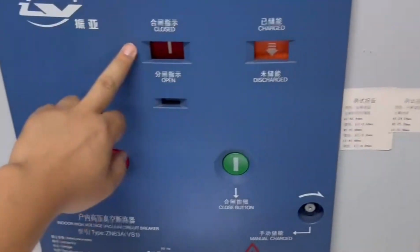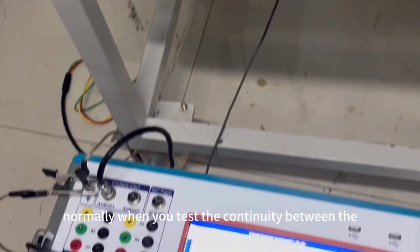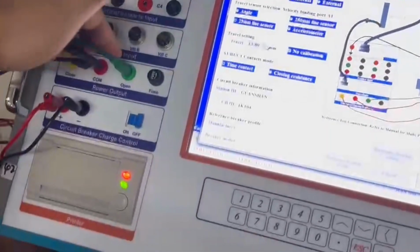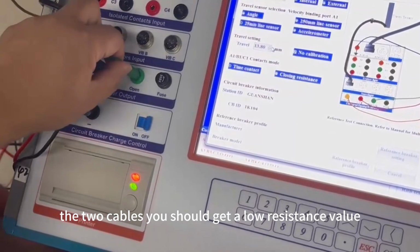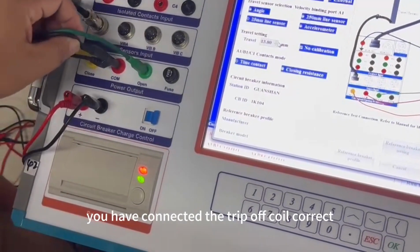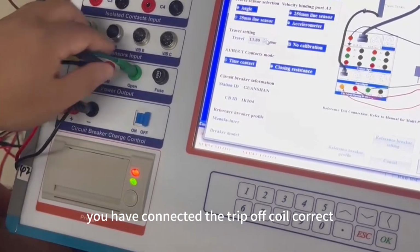And if the circuit breaker is at the closing state, normally when you test the continuity between the two cables, you should get a low resistance value. That means you have connected the trip off coil correctly.